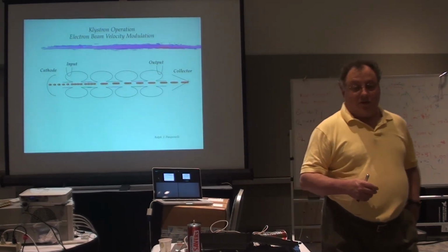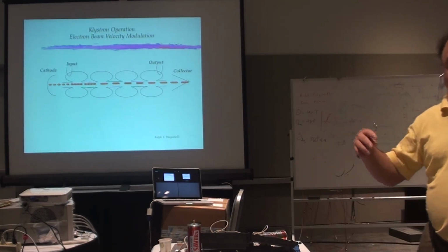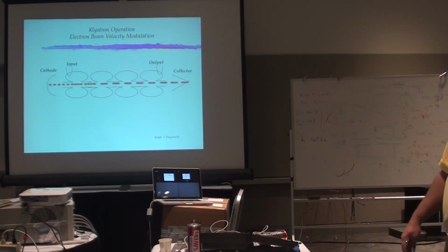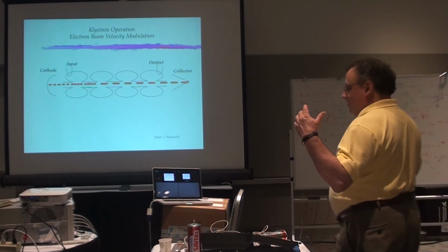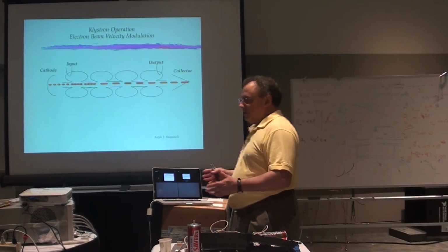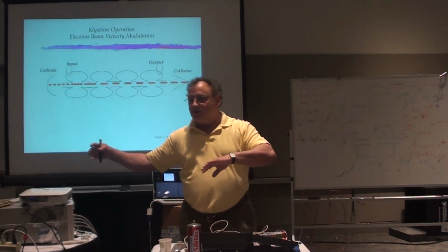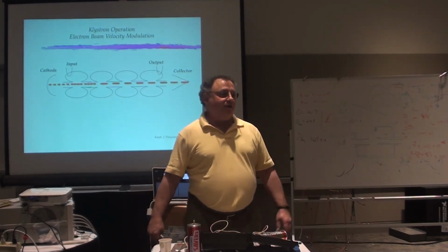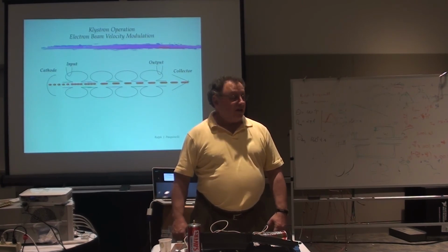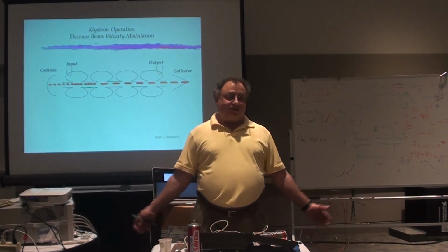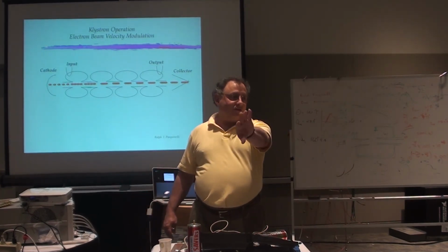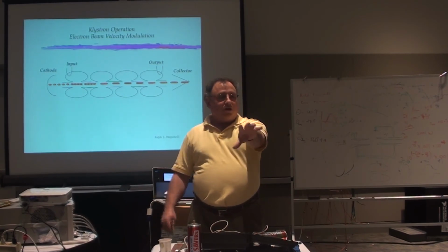So now when you run a klystron, you want to run it as efficiently as possible, but unfortunately, if you run it to where it's giving you that maximum efficiency of 50% out, as we already talked about a little bit in amplifiers, it does go into compression and start to generate nonlinear characteristics. And can you tolerate that? That depends on your system. Will your cavity filter out all this other stuff? That's fine. Where does all that reflected energy go?